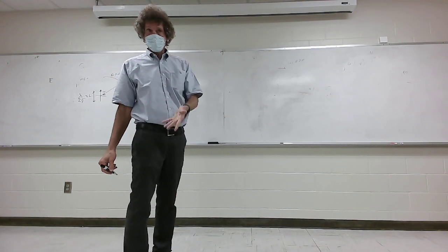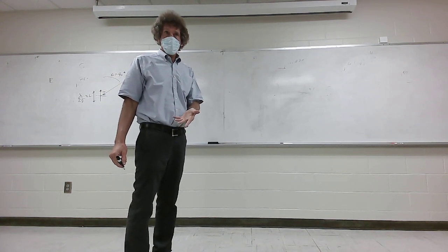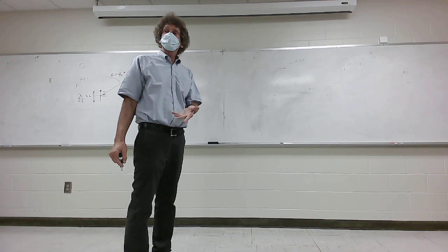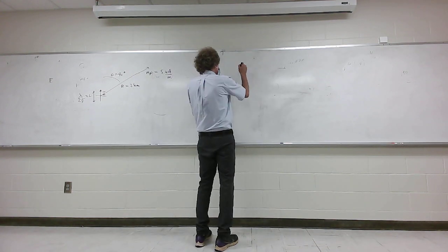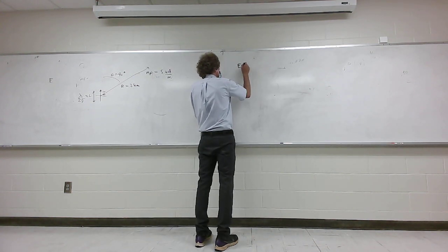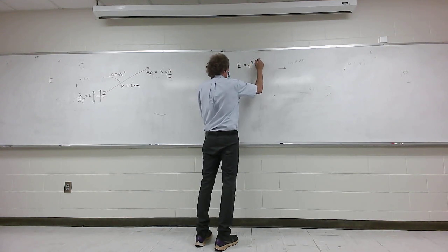Well, it's the E field divided by eta. Somebody's going to say, do we need to know the E field equation for a short dipole? Not this quiz, but you will for the test and for other quizzes, all right? Because you'll be immersed in it. So in general, the E field for a short dipole is given as, I like to do it this way, j eta beta I L over 4 pi r.